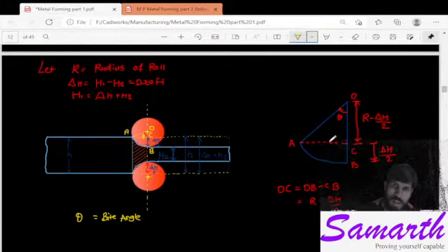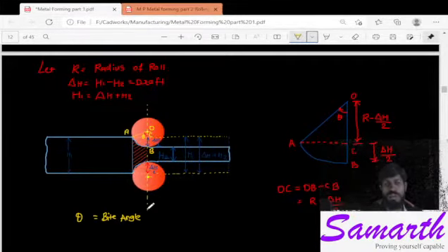And this theta is the angle of bite or bite angle, which we obtain from the point of contact between the roller and the sheet up to this point only. That means the exit plane. This vertical plane we can call the exit plane, which is perpendicular to the screen, let us say right now.